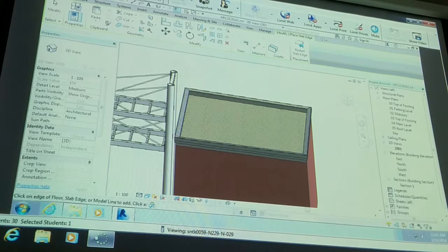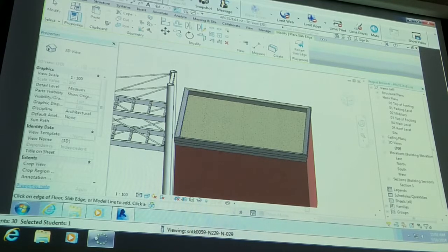So just, you know how there's one category in an assembly which is for structure? So ideally, the structural slab would fit in the same location as the material that shows up as structure in the roof depth. So those should correspond. There is some overlap in Revit, and it's the case with floors, and it's also the case with columns. No, the roof tool doesn't have a slab edge tool. It just has fascias and soffits and gutters.